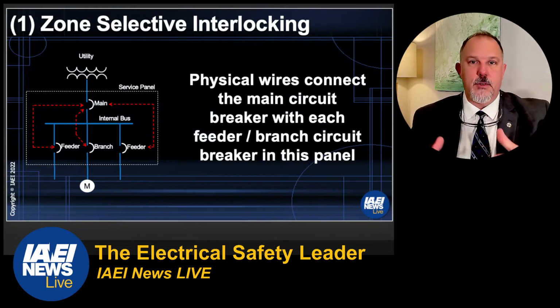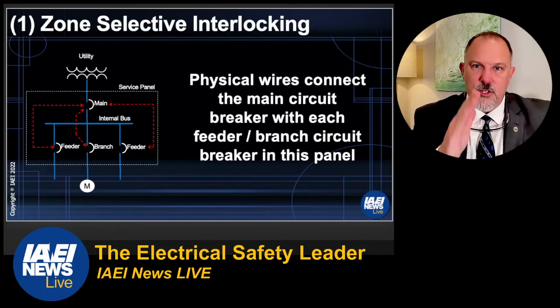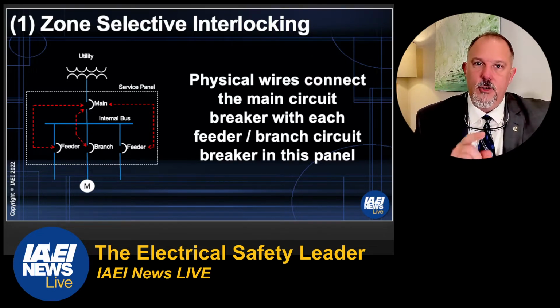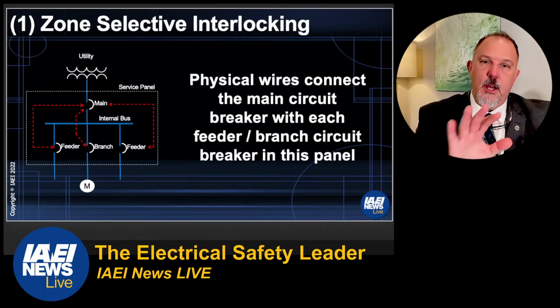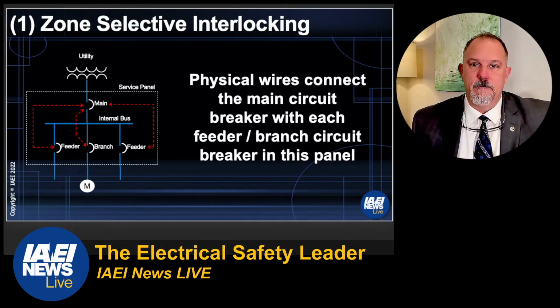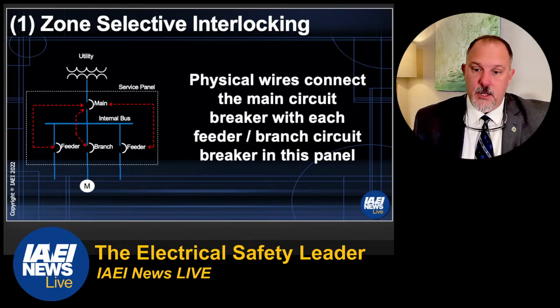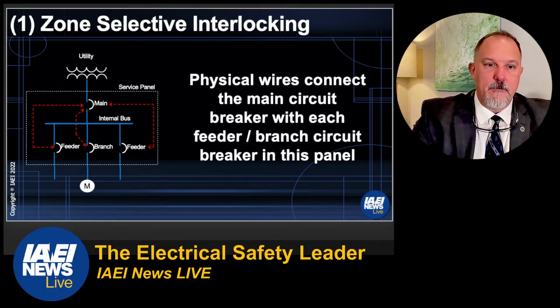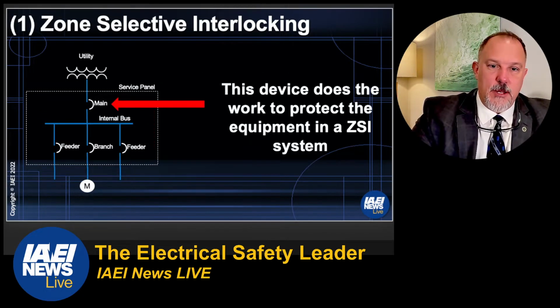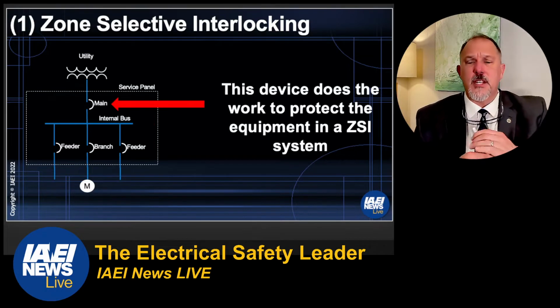You've got to focus on the settings to achieve your selective coordination goals, and then you're going to focus on the equipment protection if you're employing zone selective interlocking. All right, so now those are going to be wired together. Now, here's basically what's occurring in a zone selective interlocking system.